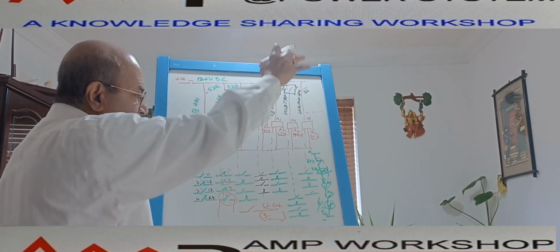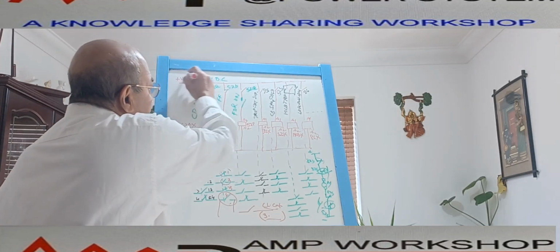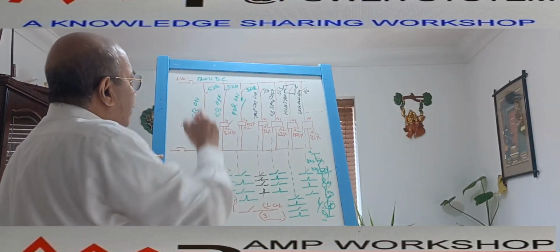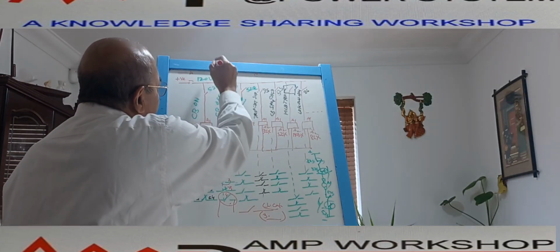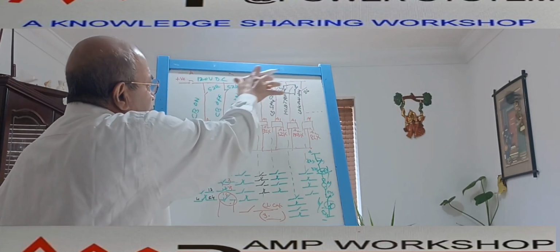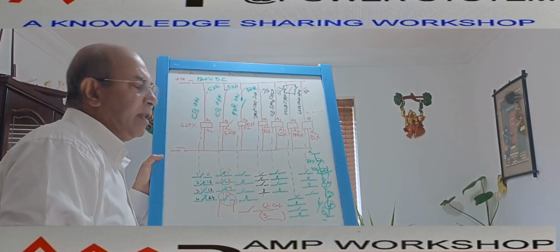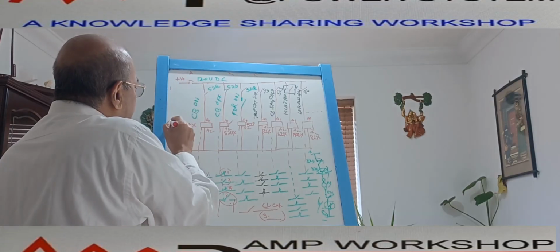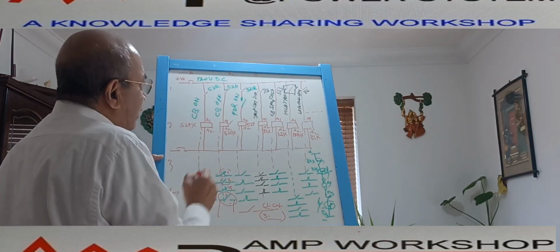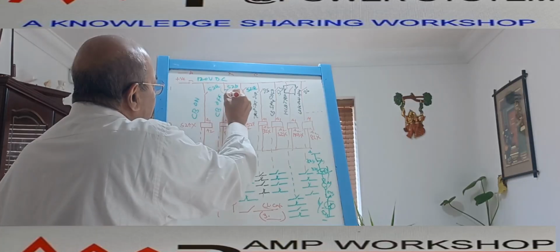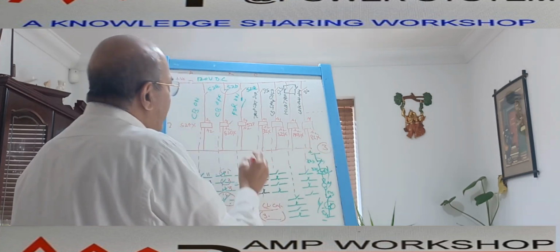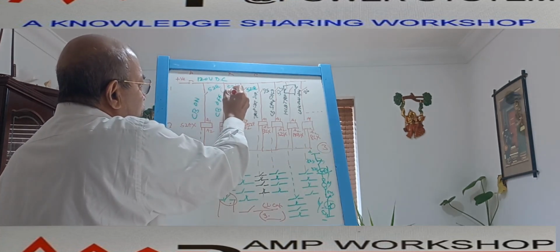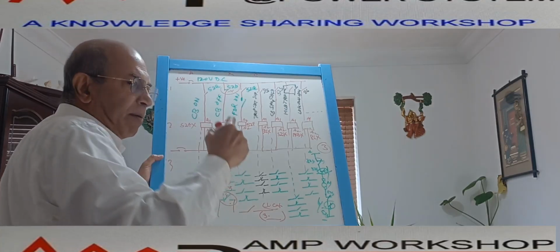Then if you see the breaker control schematic drawing, it has a horizontal and vertical reference. Suppose on this side we put references A, B, C, D, dividing the horizontal portion into areas, and the vertical portion we divide into 1, 2, 3, 4 like this. Suppose I am using this contact over here. What does it mean? Suppose this contact, 52B, is coming from page number 3.